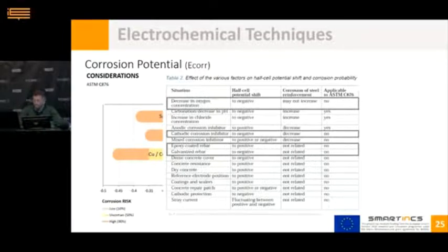The measurements should also be evaluated with cathodic inhibitors, okay, as they cause the corrosion potential again to shift to a more negative value, but it doesn't mean an increase in corrosion risk, as a reduction in the corrosion severity is normally achieved with these inhibitors.